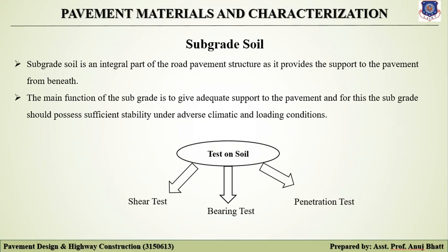The penetration test may be considered a small scale bearing test in which the size of the loaded area is relatively much smaller, and the ratio of the penetration to the size of the loaded area is much greater than the ratio in the bearing test. So this is all about the brief introduction and explanation of different types of soils.